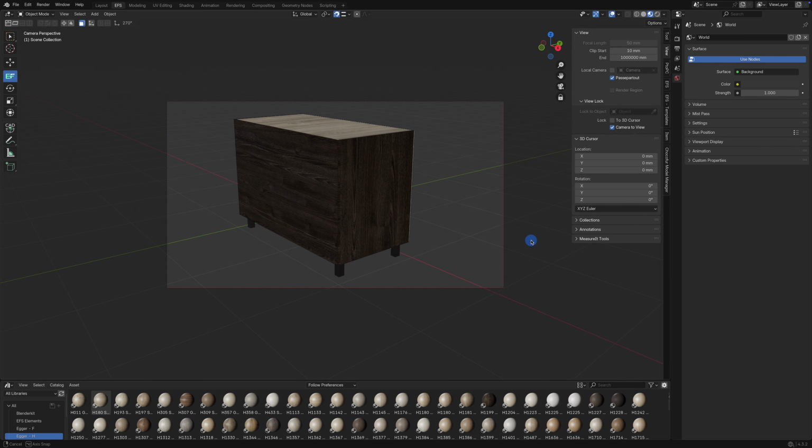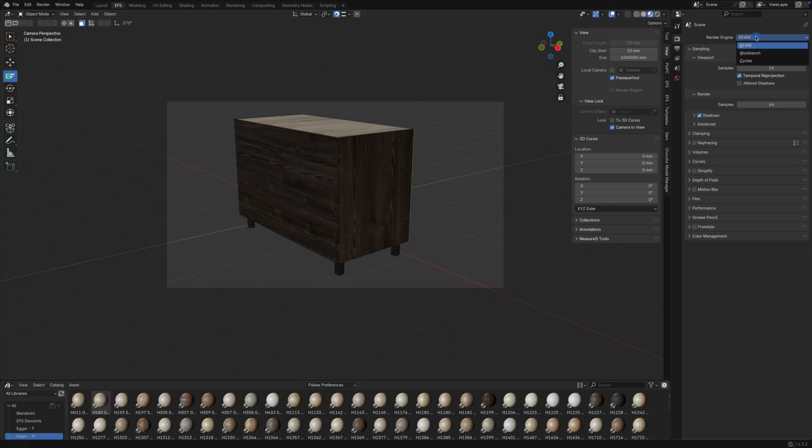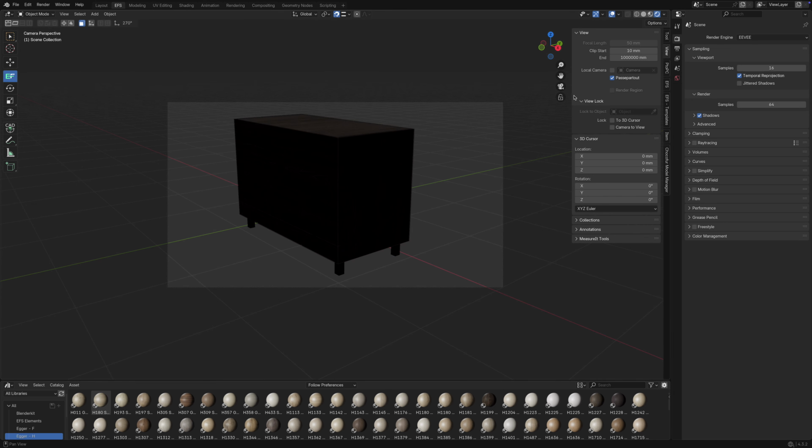Blender offers two primary rendering engines. EEVEE is much faster and great for quick previews and iteration cycles. Cycles offers more realistic lighting and shadows but requires more processing time. Switch to rendered mode by clicking the Render Mode selector to see a real-time preview of your final output.